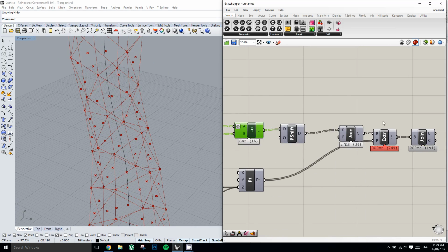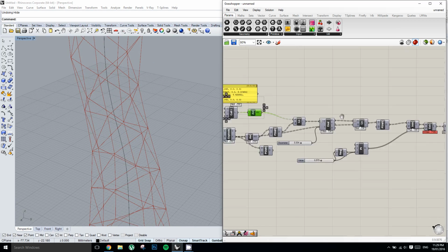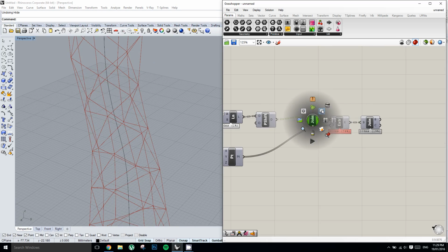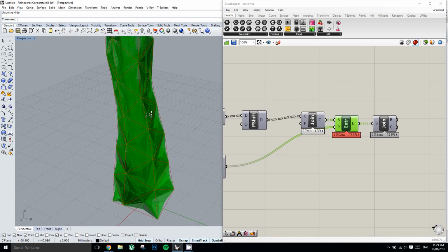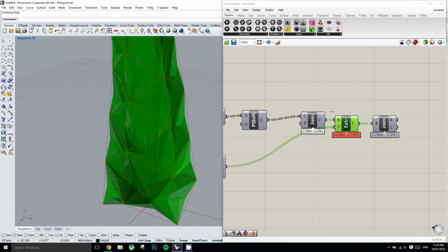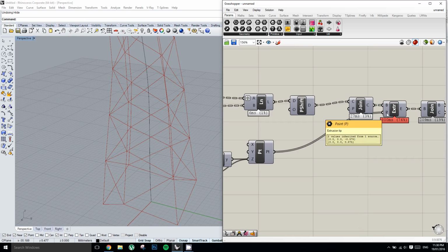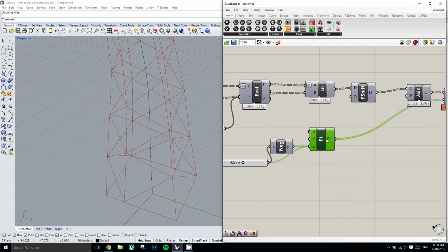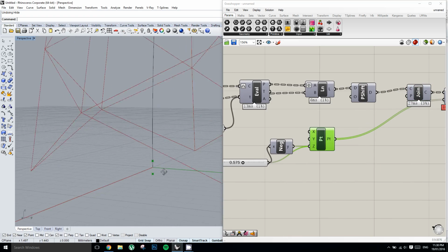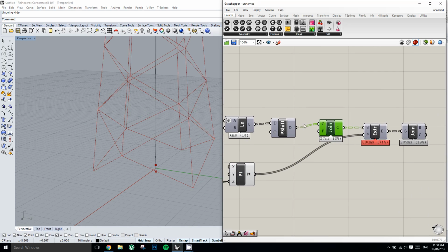Alright, so now we'll move on further down the hierarchy, and let me just turn off these things that are all working properly. Let's see, the joining is working fine. The extrusion forms a bit of a problem. Now this was probably a problem we could have expected, because basically what we're doing here is we are setting our extrusion tip for every single one of these curves to a point which is over here. So everything is being extruded to this point, when in fact what we need to do is create an extrusion point for each and every single one of these triangles.